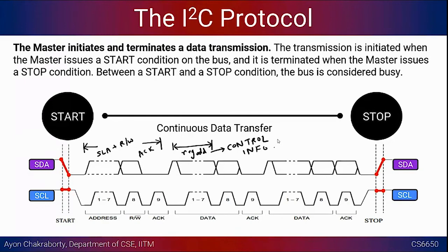Okay. And often it is the case, let's say something like an EEPROM, where you have successive memory locations and you don't want to send the address for every data byte to say where to write it, right? Often it is automatically programmed to pre-increment or post-increment or decrement.